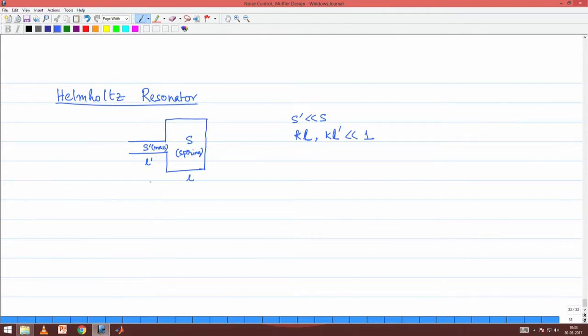So, we are basically breaking down this collection of two ducts into an electrical system. The first one, corresponding to S prime L prime, will have an inline impedance. The second one, so there is a ground line which I should draw as usual, corresponds to a shunt impedance Zs, right.